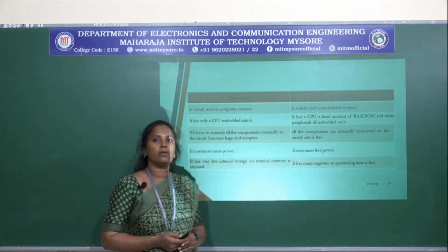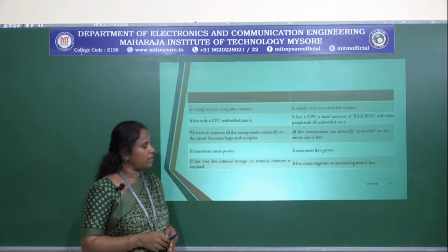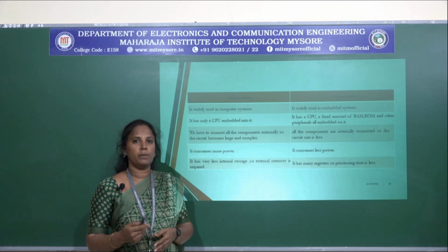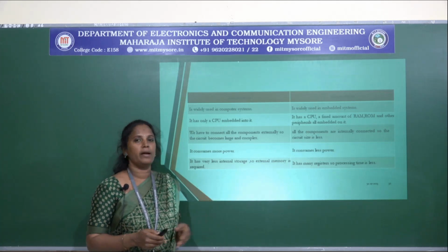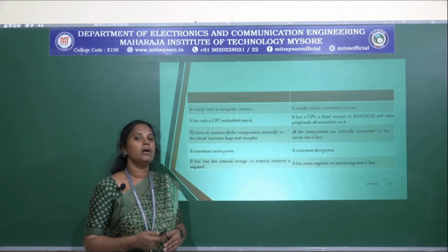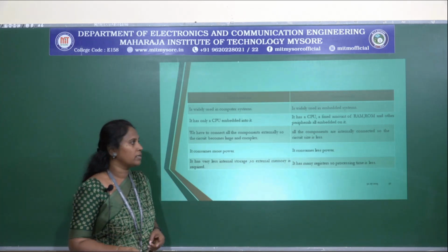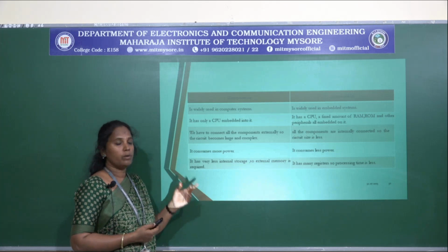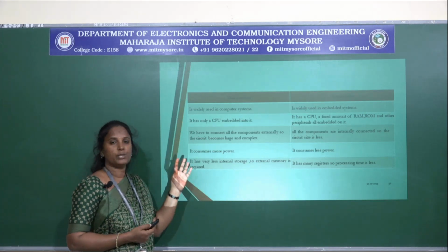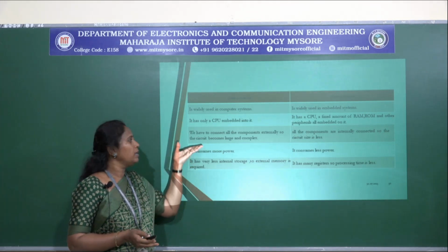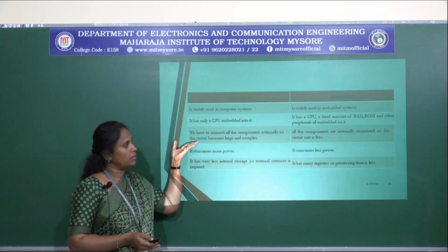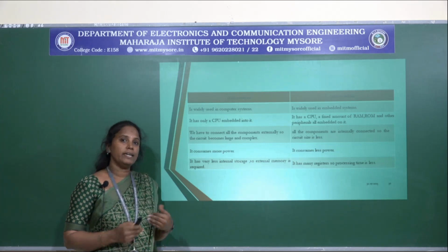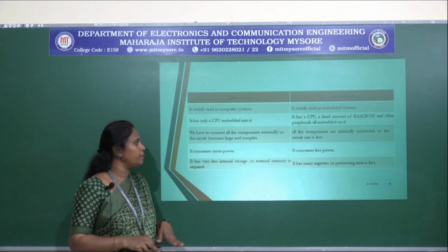In the case of your microcontroller, along with the processor it also has the memory like ROM, RAM and other peripherals like timer, counter, communication interface, etc. In a processor we have to connect all the components externally. So that's why the complexity involved is larger in the case of processor, but in the case of your controller, all the components are internally connected. That means it is already inbuilt.